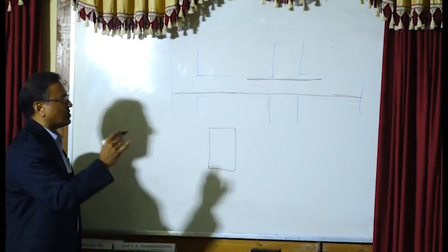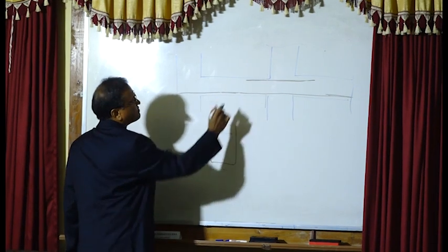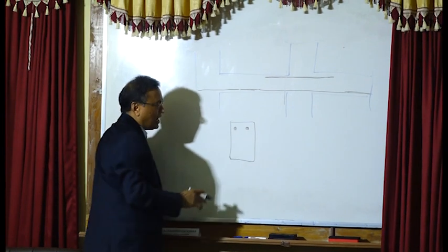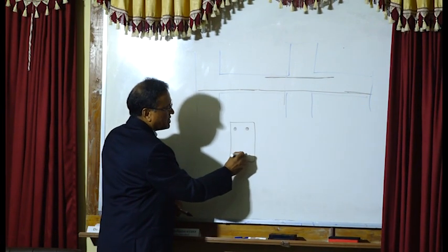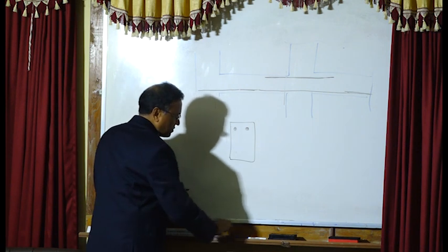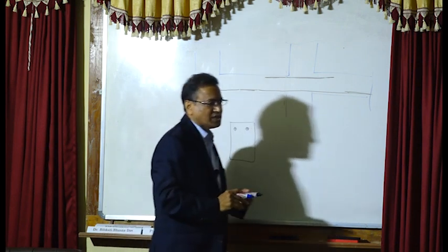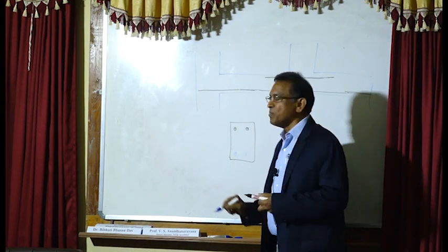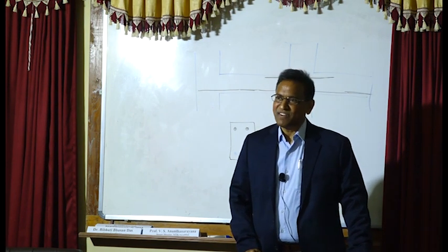Now at this point, if I cut a section, let's say that's my cross section. It has flanges, of course, and you have these bars, and you have these bars as well. So what I mean by discounting the compression bars, or bars in the compression area, is you cannot use these bars for moment capacity. That's what it means.